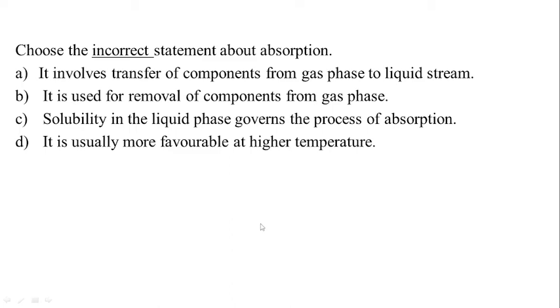If you can control the submergence, quite naturally, the extent to which the liquid phase is cooled in the condenser will change. Now, there are certain columns, for example naphtha stabilizers, whose top product is basically a liquid which is a mixture of propane and butane, which is LPG, and there is a small quantity of non-condensables which will be leaving from the top of the condenser or from the top of the reflux drum.